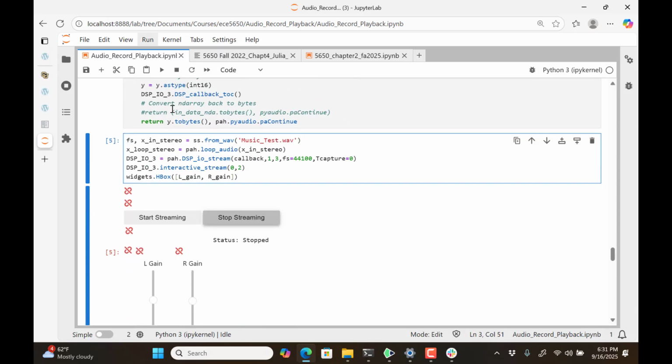And we get to specify the sampling rate, and these 2 numbers correspond to the input from the microphone, which we're not going to use, but we have to fake the audio system into thinking we're using it so that it can function properly. And then we're going to come back out on 6. And this last parameter here just tells we're going to loop indefinitely by not looping for a second or 20 seconds.